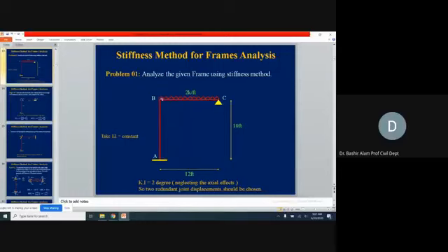How is this beam going to deflect? It is going to deflect in a concave shape here near this support, because of this loading. Now if we draw a tangent and draw a curve starting from the original position to the deflected position, you see how the actual rotation is going to be. It is going to be counterclockwise.